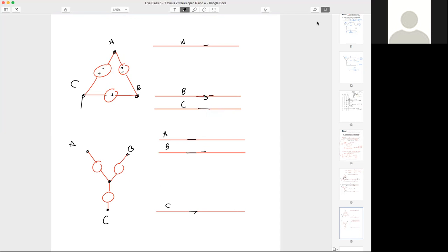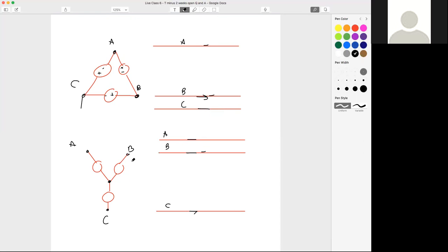All right, let's look at our voltages. Who can tell me where is my phase voltage of my source? Everyone good with that? It's going to be from top to the neutral. They can say, okay, what's the three-phase line value of the source? But really, what's happening here? We have three separate sources tied together at the center, and all three of them are 120 degrees out of phase, right? That's what's really going on here.